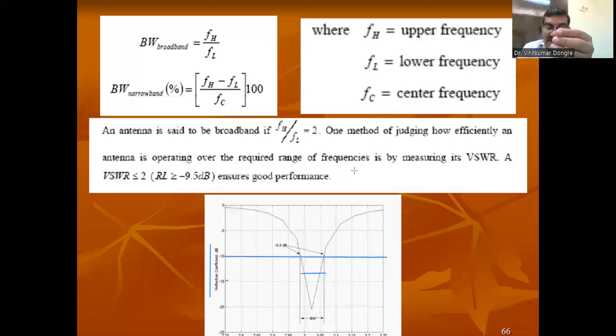That antenna is receiving. How will we ensure it? What is the mechanism you have? This is one of the mechanisms. If you look at this graph, the higher frequency is 868 and the lower frequency is 866. Then you are getting a 2 megahertz bandwidth, with 867 as the center. So you are assured that this antenna you have designed can be used for RFID application.